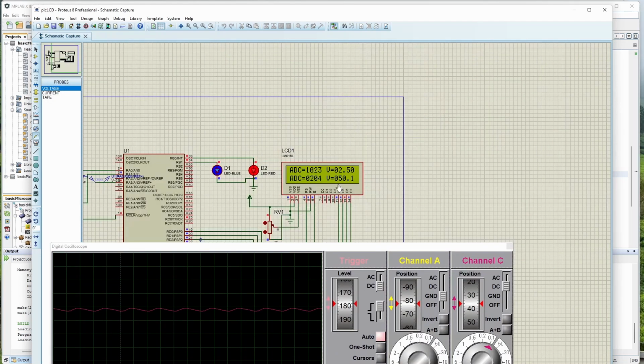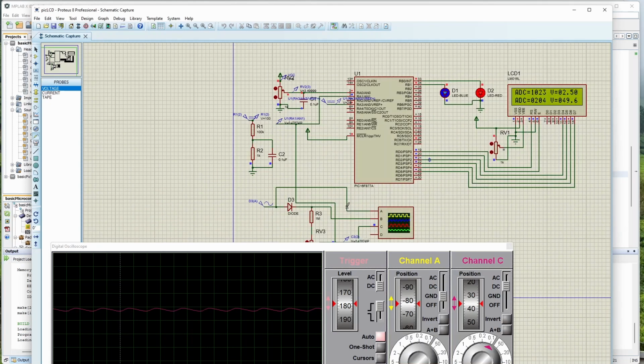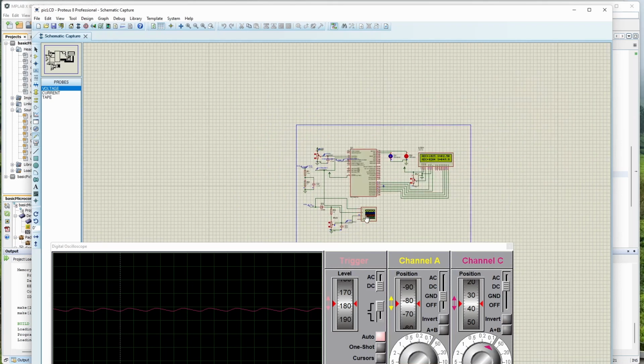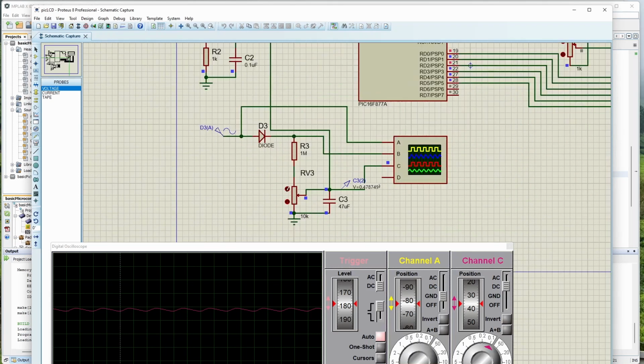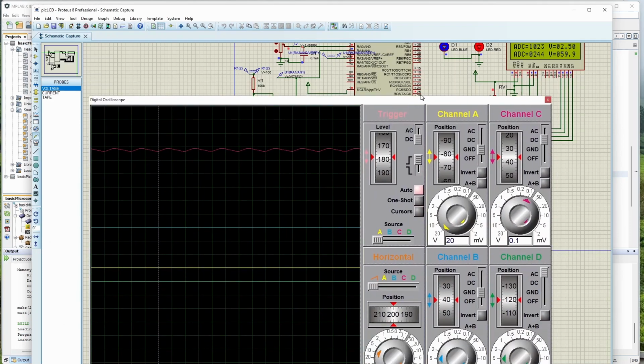So now what you have to do is, this one you have to link it to the supply voltage. So into 4 or 5, practically put a multimeter here and decide the multiplication factor, and over that if you want some more fine tuning, you can do this or not even use the pot. Okay, and the last bit of tuning, if you want to do on the side, like just slightly change it. If you were showing for example for 220 it was showing 240, you can just tune this one so that you get exactly 220. Hope you are able to understand that.